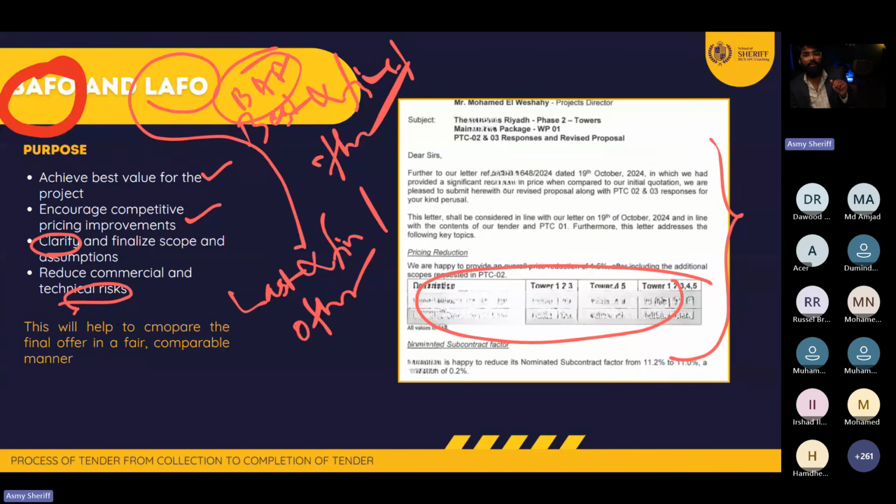So tell me, where did we start? We started with preparing the tender document. Then we shortlisted the contractors. We secured their EOI and their NDA. Then we did the PQQ. Then all the tender documents that we prepared even before starting our shortlist, the ITT, volumes 1, 2, 3, 4, 5, we floated to them, and we invited them to the tender clarification meeting, or pre-tender meeting. Then they raised many queries, tender clarifications, tender bulletins. Then after that, they submitted their tender and we opened that.